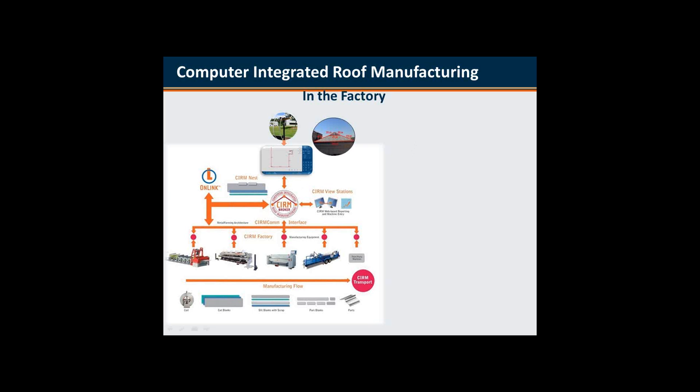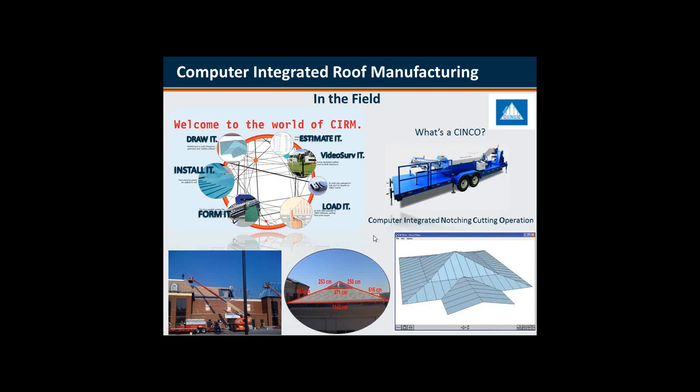The other interesting thing is that the current way our market makes these roofs is they make a parallel panel. If you go back to this slide here, they will produce a parallel standing seam panel, and they actually have to go up to the roof. And this is not tape measure. This is actually to make it fit on the roof. They have to go up here and make a longer panel that comes up to this point. Then they have to use cutting snips to go through and cut this piece here.